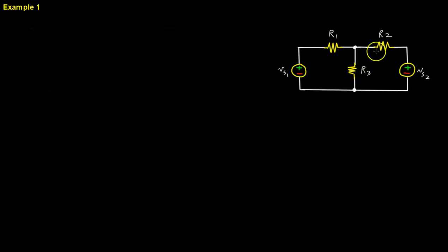We have this loop, and also a larger loop that encompasses the entire continuous branch that you can see here that I'm tracing out. Now, for mesh analysis, as the name suggests, we should define some currents flowing inside of a mesh. The way we do that is usually we go clockwise. So we start going this way, and we define a current circulating inside of this mesh here. Then we can do the same thing in the other mesh, and I'm going to label it I1 and I2.